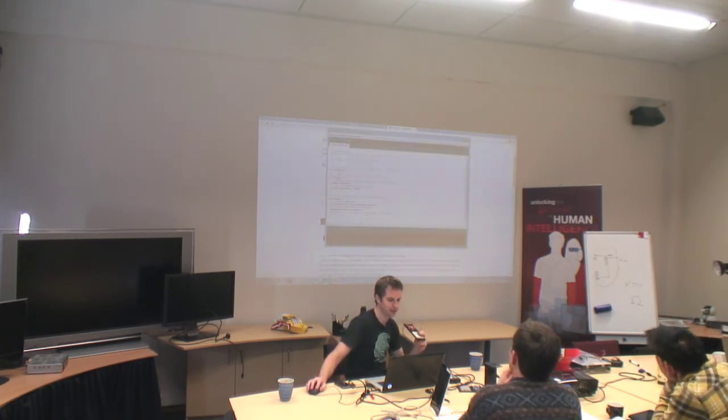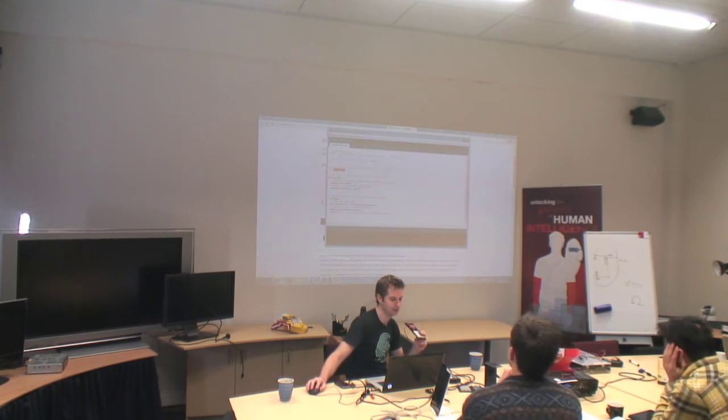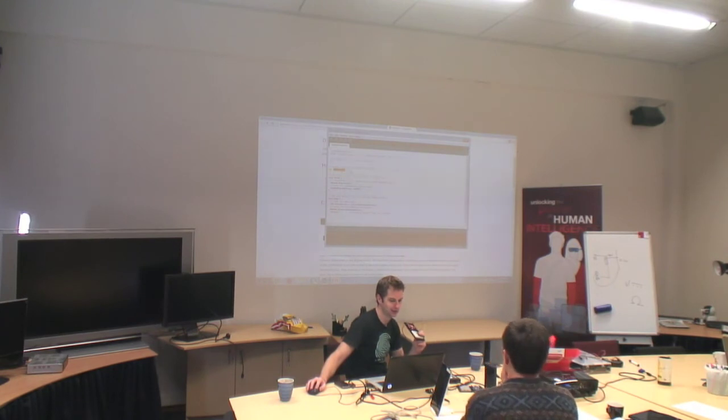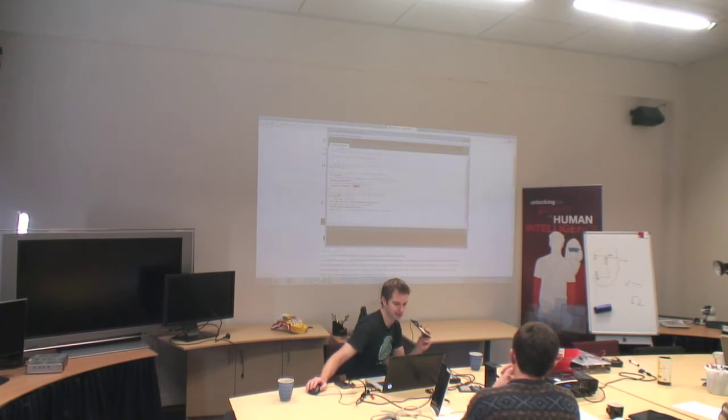Here we define the button: digital pin 2 has a push button attached to it, so we say number 2, and Serial.begin 9600. I didn't say before, but this is the speed that the serial port will operate at. This is 9600 baud, which we're usually going to use. It means it can send 9600 bits per second, which is kind of slow, but you're not going to be sending huge amounts of data from the Arduino anyway, so usually that's fine. Like before, we saw pinMode, and then we gave it a number and output. Now we're saying it's input. We're going to read the value off this pin, not send data out of it.